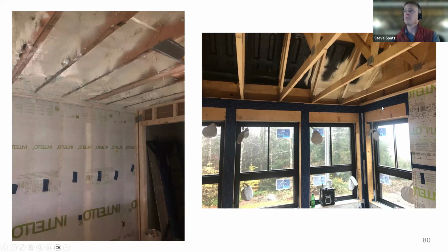Another example here of those framing and interior construction details. You have a dense packed cellulose cavity where you have vapor control of that Intello installed over the dense packed cellulose, but then you have a whole corner of windows. And each of these, the gaps that would occur between your header and your king studs and your jacks, are pathways for moisture vapor to get through, stacking of lumber, which could get to the sheathing behind it, which could create pinch points for moisture transport and moisture accumulation. So in this example, what we did here was use an airtight and vapor permeable tape that would keep moisture vapor and air from getting into those, but still allow for drying potential back into the room as well. So it's stitching together the details that matters.